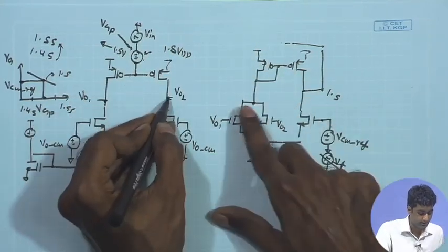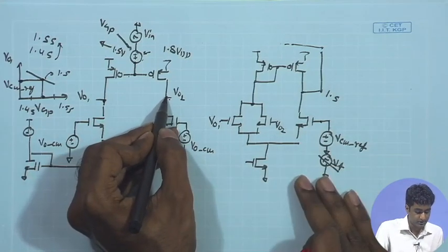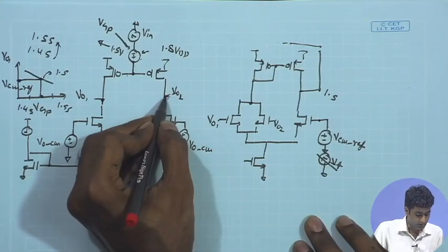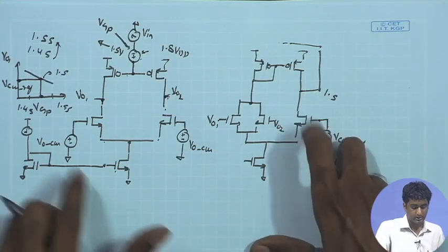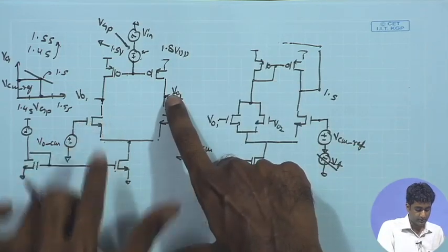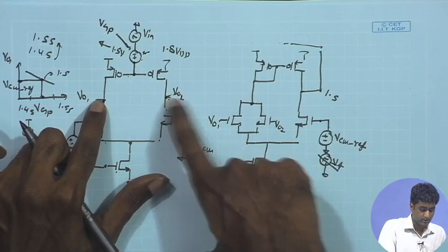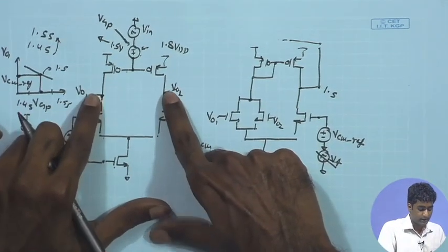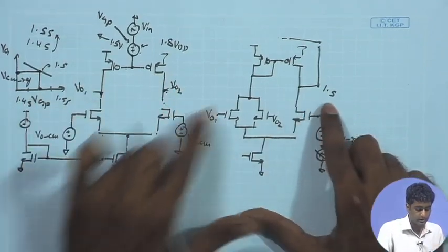So, if you have a cap connected, in the compensation scheme, between the outputs over here and the output at this point, that can lead to Miller multiplication between the caps, between the input stage and the output over here, but that is however going to load the main amplifier also, which is not very advisable.